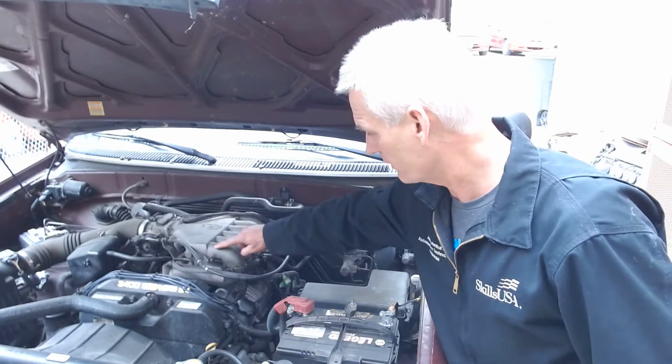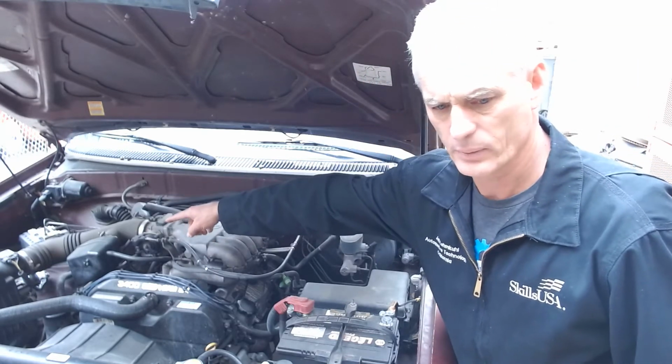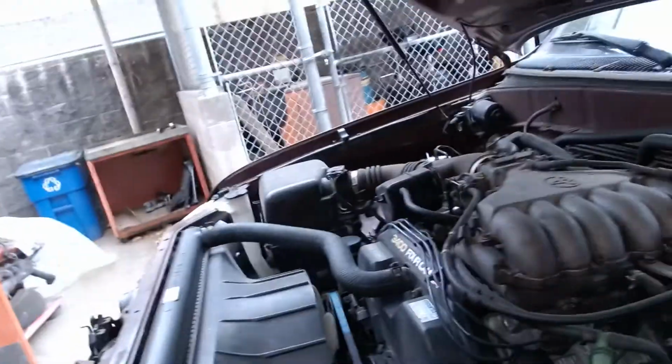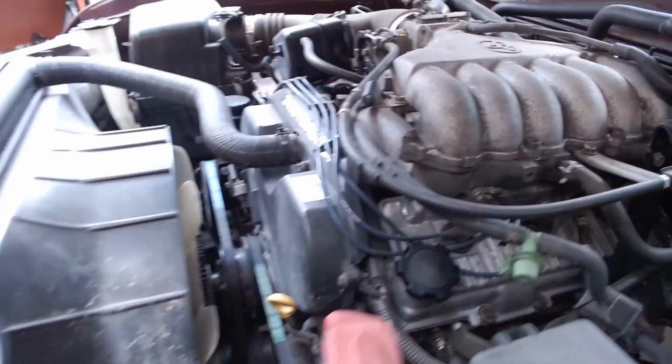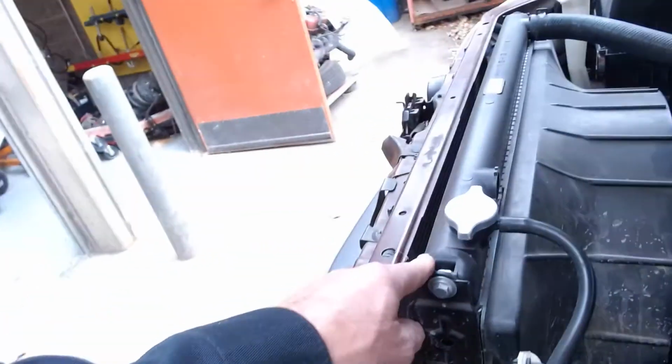Here's the intake manifold with the 6 tubes, because it's a V6 engine, 3 cylinders on this side, 3 on that side. The belts are towards the center, so we know it's a longitudinal engine. You can see the belts up there are pointing towards the front, and this has a belt-driven fan that you can see, and you can see the aluminum fan clutch, and there's a nice big fan shroud for cooling, and then there's the radiator here.